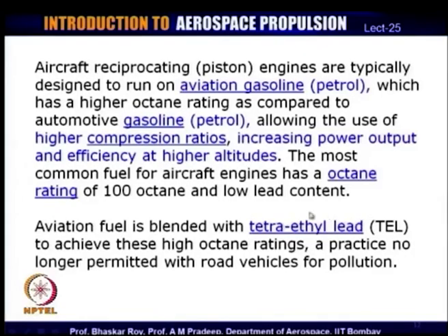In land based automobiles, this addition of tetraethyl lead is now banned because of environmental issues, but in aircraft engines it is still practiced, because aircraft mostly fly at very high altitudes, and we require the high octane rating necessary to operate at very high compression ratios at high speeds for producing high power at reasonably good efficiencies.